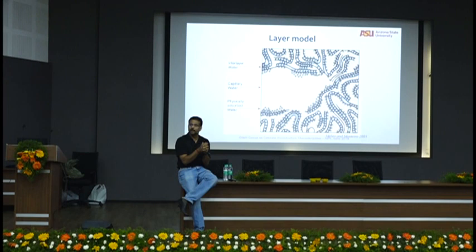When the water molecule is not constrained by anything else, you leave the water free, and when you give heat equivalent to 100 degrees Celsius, it will change its phase from water to gas. But if you are constraining water in small pores, this is like holding somebody trapped in a room, holding somebody trapped in a small place. 100 degrees Celsius is not enough. You need to give even more energy for that attractive bond between water and the surfaces to break.